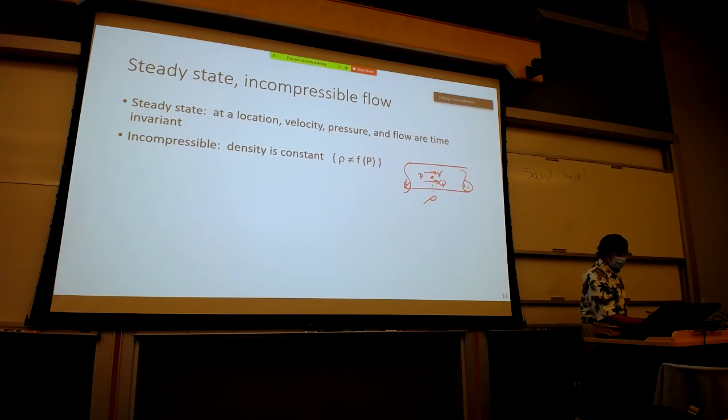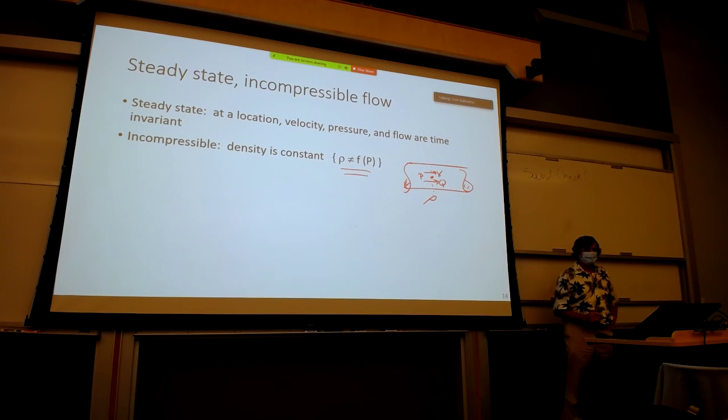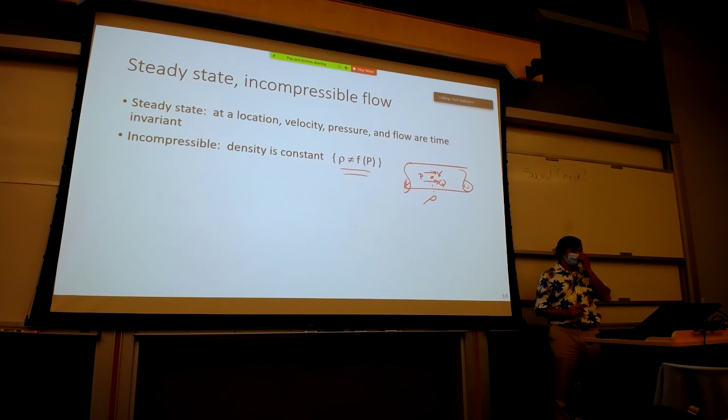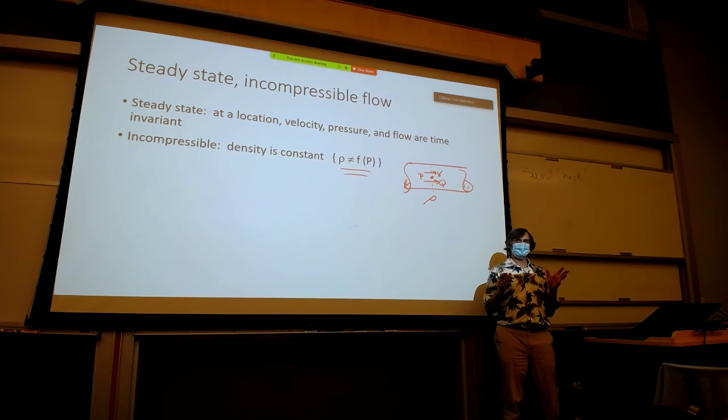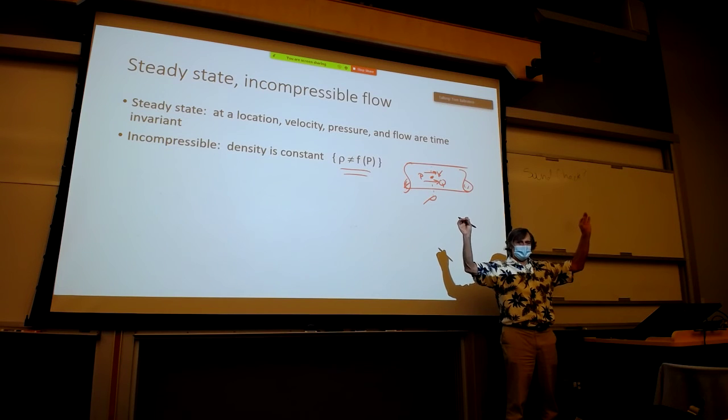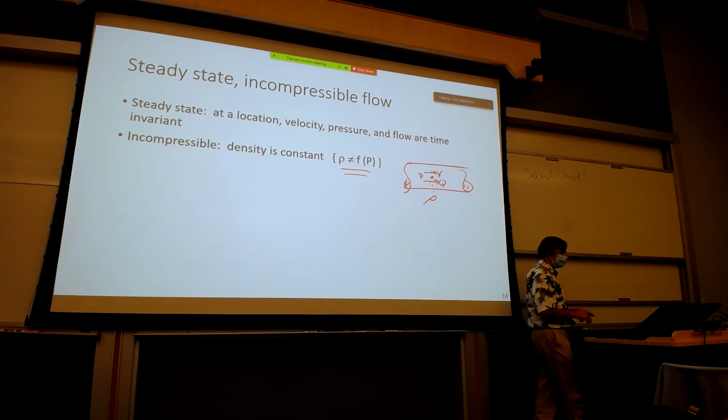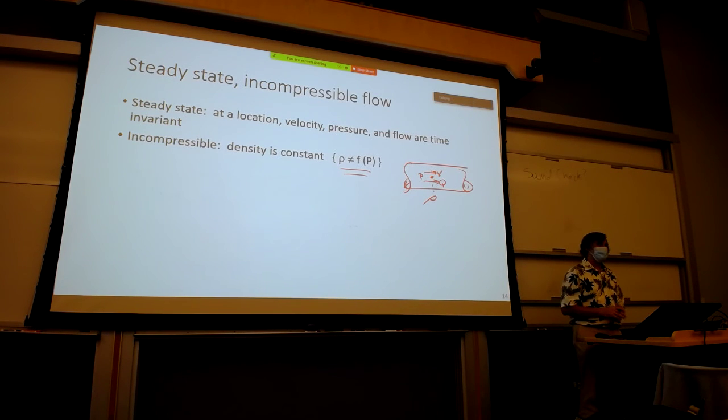So the density, by being incompressible, is also not a function of pressure. For gases, that's not true in general. Gases at very low velocity, for example in the ductwork of buildings, can sometimes be assumed to be incompressible. That's not an uncommon assumption when you're designing HVAC systems.